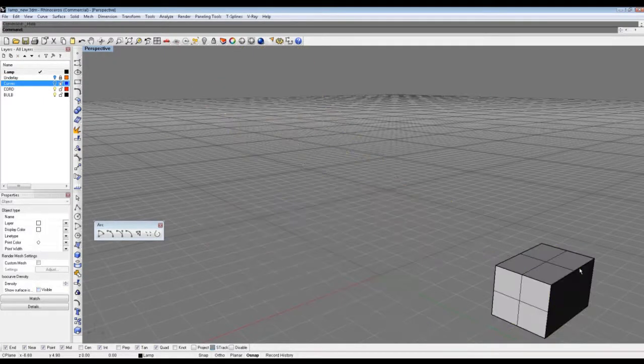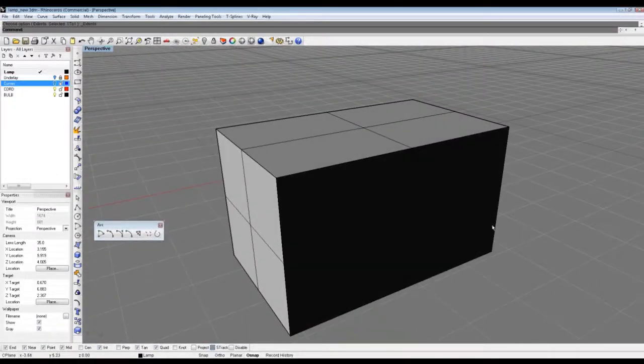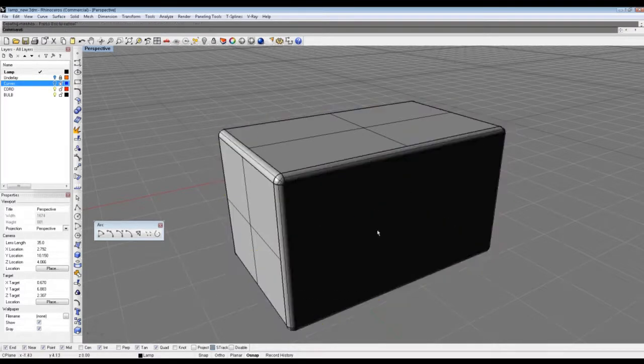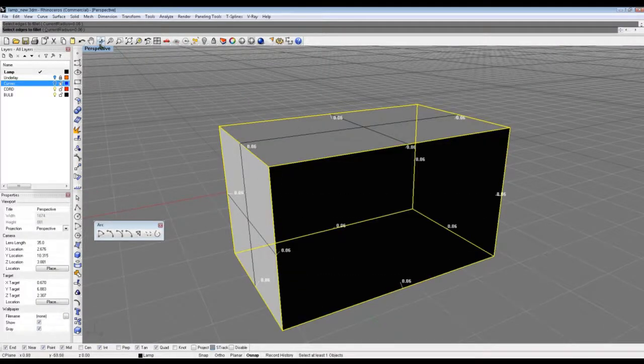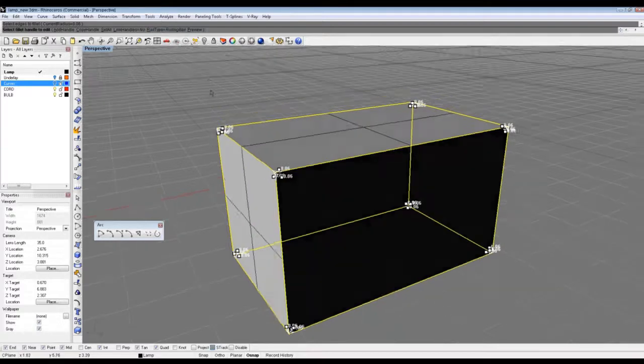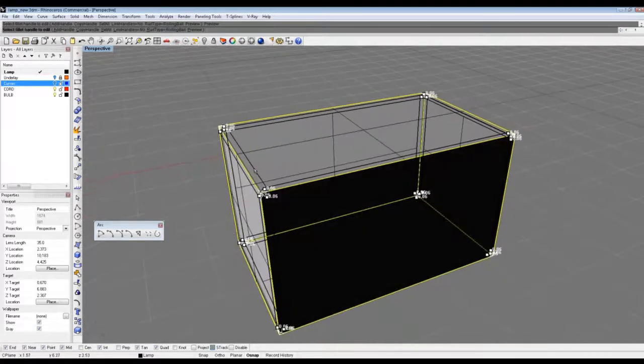When you're working with a box and you fillet it, we'll do 0.06. It looks great, okay? But I want you to look at the actual command line. I hit enter, and before I hit enter again, you can actually preview what that fillet is going to look like. And all I did was click on preview.